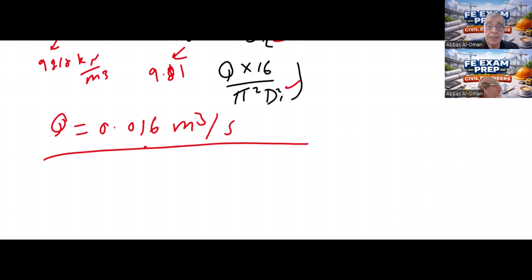Now in the venturimeter, as well as in other flow measuring devices for pipes, we need to know the full flow diameter and the small diameter, the orifice or the throat or the nozzle, and the pressure drop. We can then determine the flow.